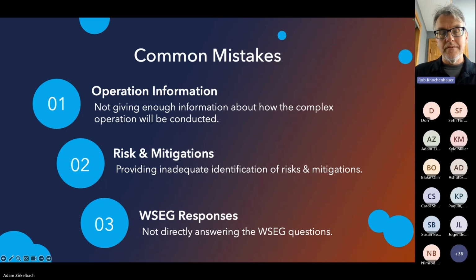In the case of the performance-based requests that we put in and have had success in getting approved, we identified the possibility that we're going to fly over roadways. If you were to put together a performance-based request and not fully describe the types of areas that you're going to be operating in, or gloss over things like roads that will provide an elevated ground risk that you simply don't address,